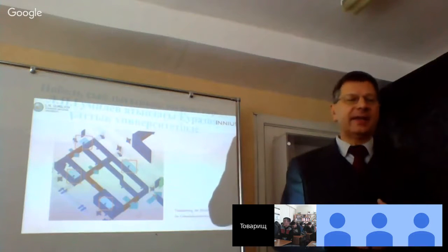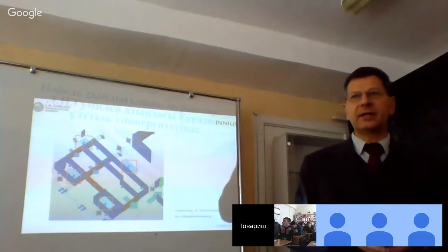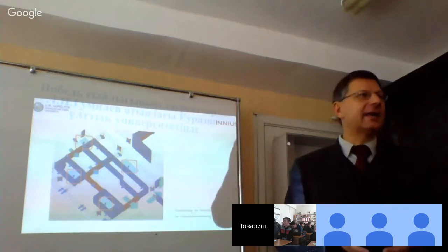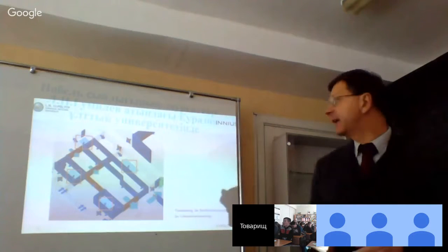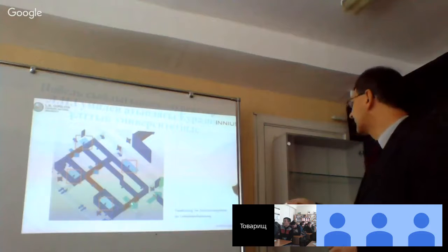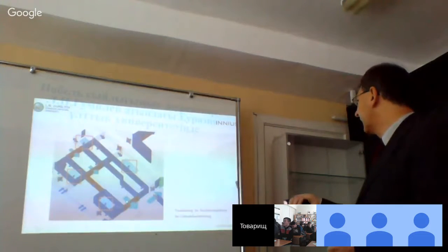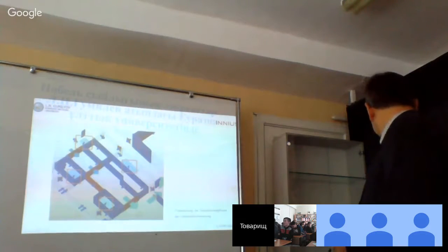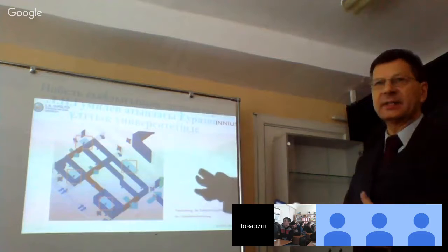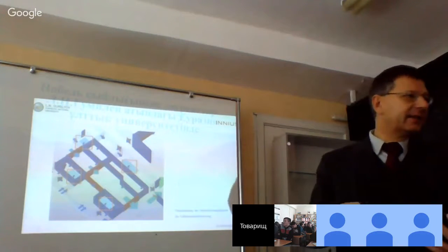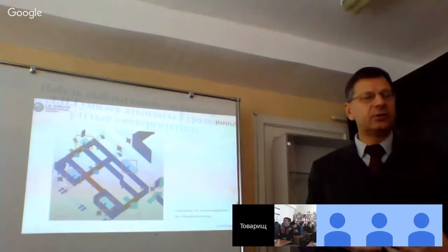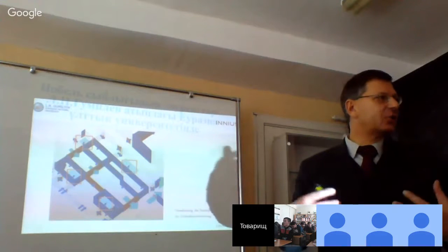And because IFC is object-oriented, you can create your own elements. In this case, we create arrows depending on the flow direction and the quantity, and place them in openings and doors. And so you can use the model, including the data, generate new elements, and show what happens.